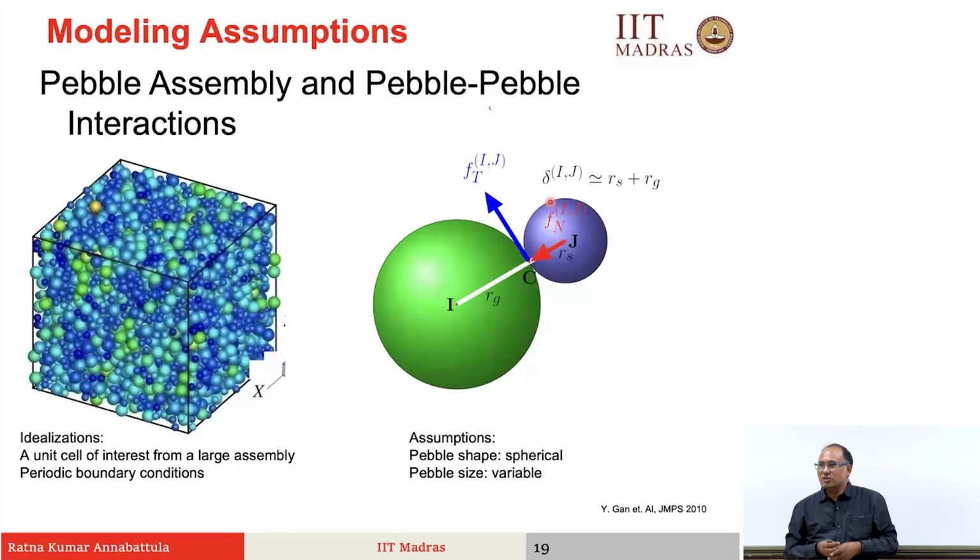So, imagine you are computing that force between the two particles. You know that they cannot interpenetrate, right, but numerically we can allow them to interpenetrate, and that amount of interpenetration allows you to compute what is the force acting. So, imagine a spring between the particles and you are pushing, the stiffness of that spring offers resistance, isn't it?